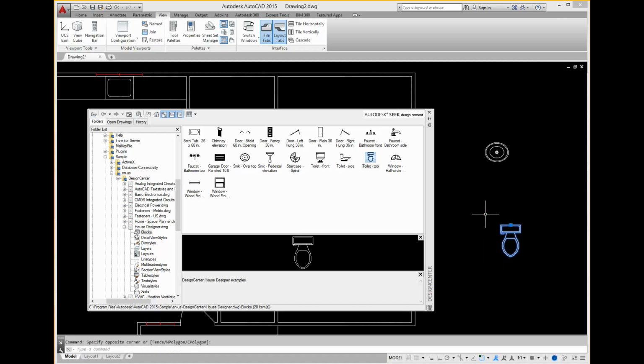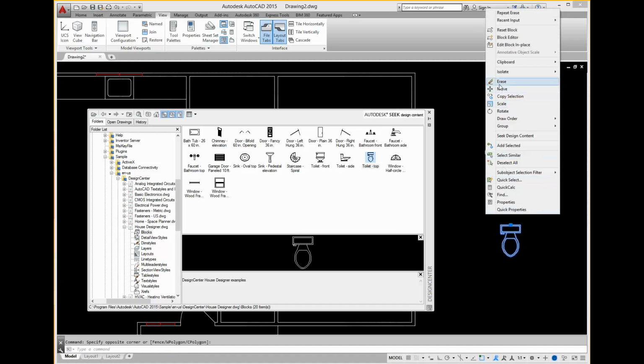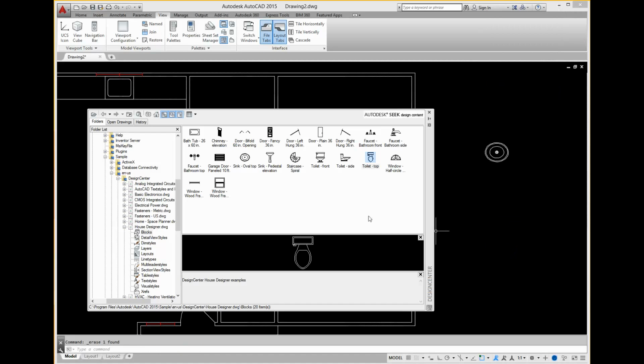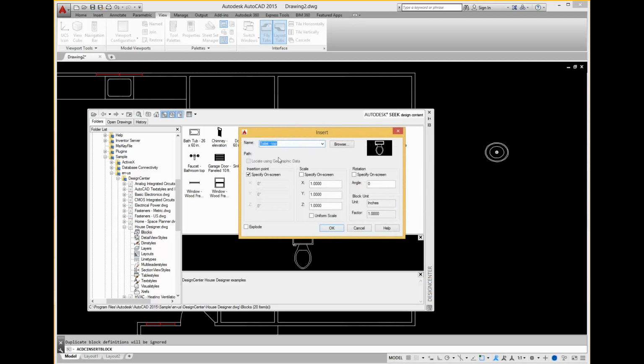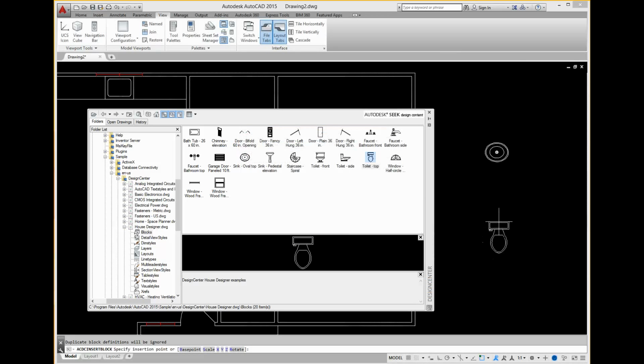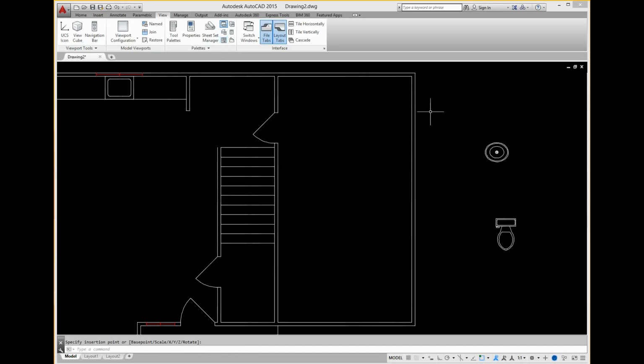And as I talk about in the book, AutoCAD often has these kinds of glitches. One thing you can do though, if you have that problem, is to highlight it, right click, and click on this insert block. Then you'll get this insert window, and then just click OK, and then just come over and click. So if you get locked up in there, there's a way to get out of it. So now I'm going to close that.